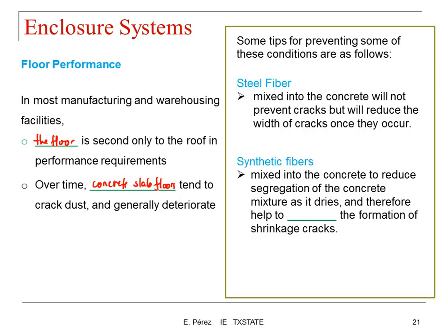Synthetic fibers are also mixed into the concrete to reduce segregation of the concrete mixture as it dries, and therefore help to reduce the formation of cracks. And this is something that you can also see in houses in this area.